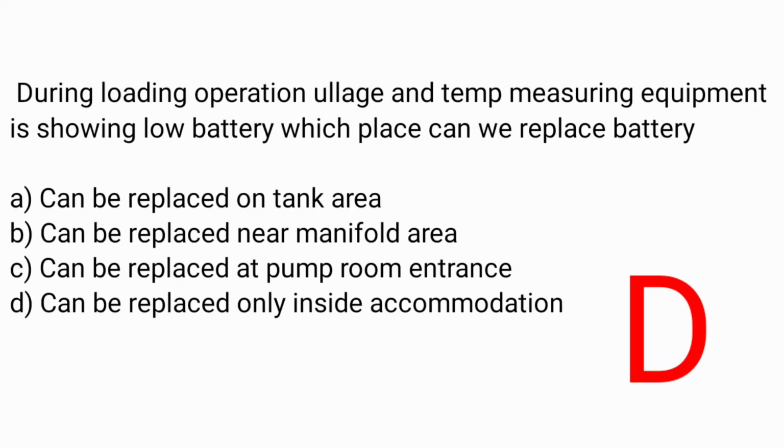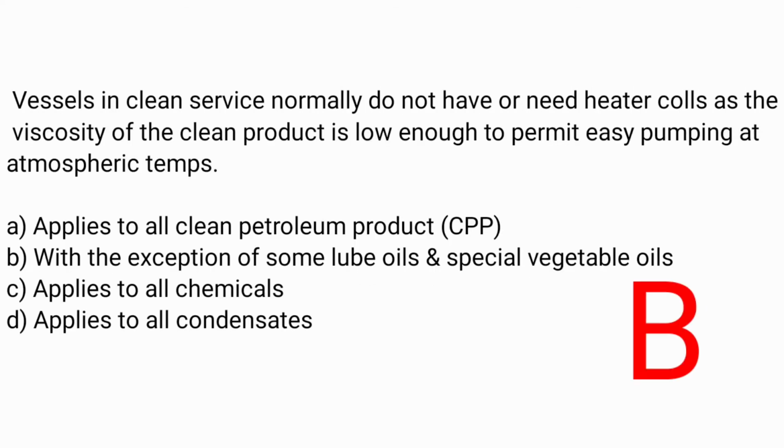During loading operation, the ullage and temperature measuring equipment is showing low battery. In which place can the battery be replaced? Answer D, can be replaced only inside the accommodation. Vessels in clean service normally do not have or need heater coils as the viscosity of the clean product is low enough to permit easy pumping at atmospheric temperatures. Answer B, with the exception of some lube oils and special vegetable oils.